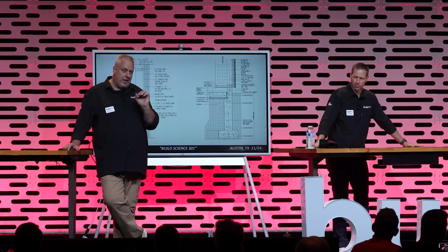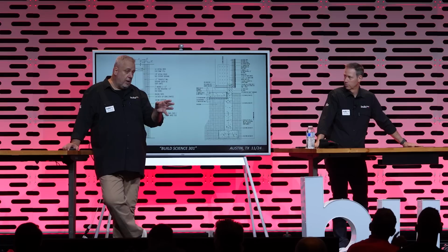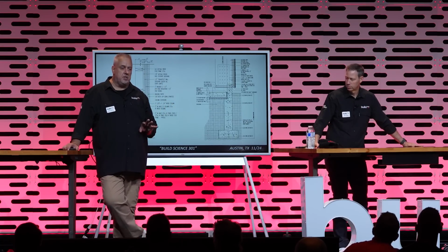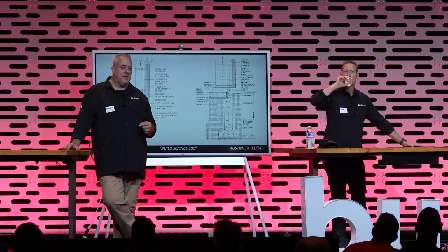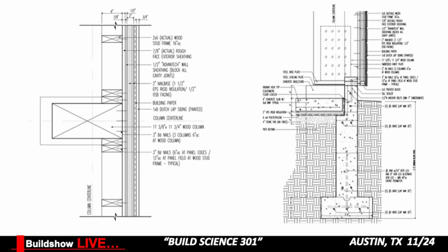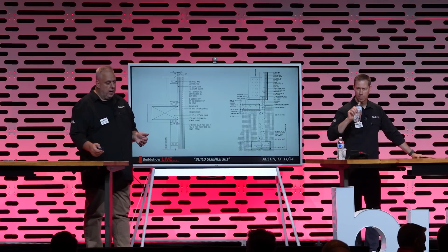It's a wood moment frame with steel plates inside, 2x4 wall, and we did exterior insulation. Now we didn't do high levels because we call it kind of semi-conditioned. It's still probably 65 plus inside, and we have solar on it, so it's a total 0 energy product. We actually pipe electricity back to the main residence and pool house from the barn. But you can see here the plan detail and then the section detail. You can see on the right side there, insulated slab, insulated on the outside. We do have some areas that were a little bit of a challenge, but this moment frame was a real challenging system to pull together.